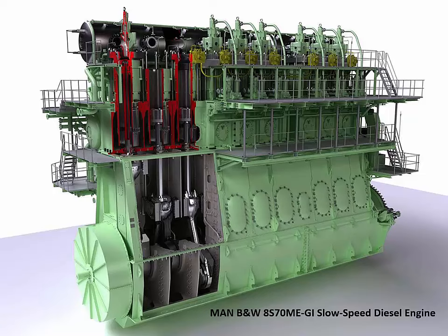With these large engines, you're talking a very high volume of air, and that air is injected into the cylinder at the proper time so that it will run in the ahead or astern directions, and it would follow the firing order of the engine to simulate the burning of fuel in that cylinder.